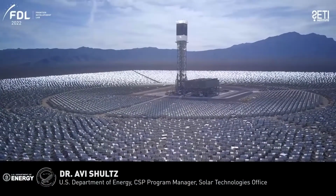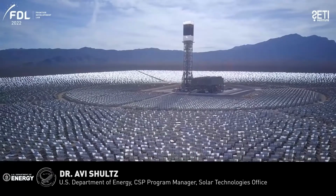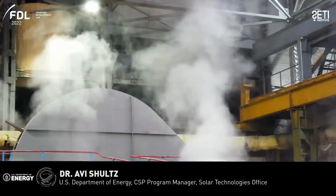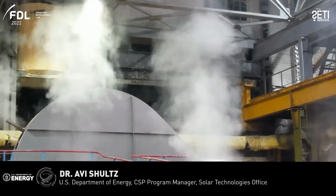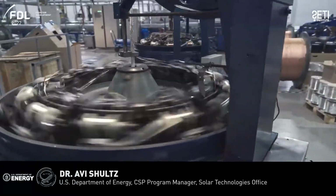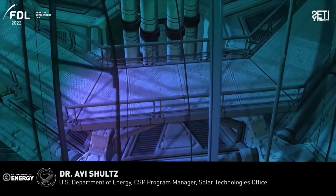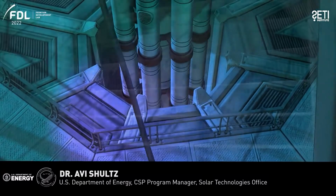Concentrating solar thermal power technology, known as CSP, generates electricity by using mirrors to reflect and concentrate sunlight onto a receiver, where a fluid is heated, stored, and then the thermal energy is dispatched to power a turbine. Traditional power cycles use steam as a working fluid, but advanced turbines that use supercritical carbon dioxide have the potential to be lower cost, higher efficiency, and utilize dry cooling, which helps to conserve water.